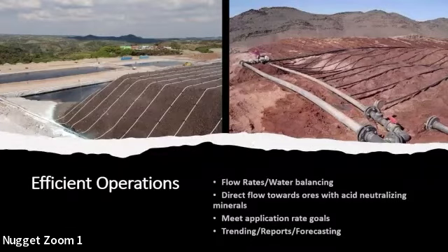Here are the shear wave velocities that were measured from the downholes. And here are some of the points from the dissipation tests that were carried out. Those results were also compared with the samples taken to the lab for basic geotechnical evaluations such as gradings and moisture content, which was one of the focuses that we were facing.